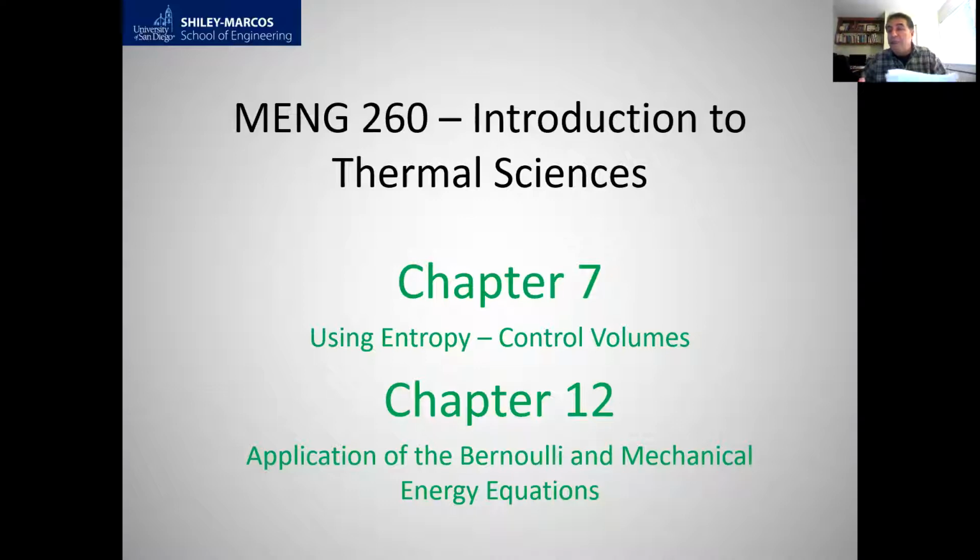And also, my friend, let me tell you one point in thermodynamics. Some of you are still not clear on this concept. If we are dealing with ideal gases, you apply the ideal gas law. Do not apply the ideal gas law to a liquid because it won't work. You need to find the enthalpy or the internal energy based on the given temperature and pressure, using the proper tables.